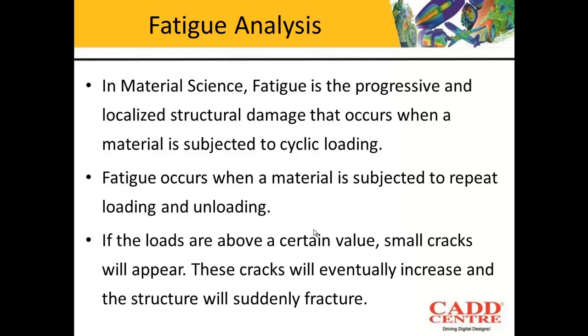So when you start loading and unloading the design, wherever the design is weak, cracks will start to develop. Initially they are all small cracks, but as the cyclic loading continues, these cracks will go on increasing, and then a certain point will come when the structure will fail.